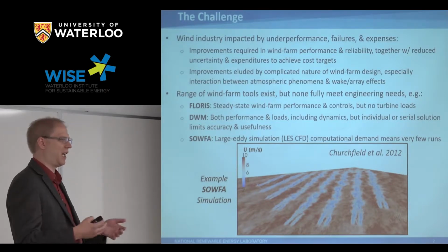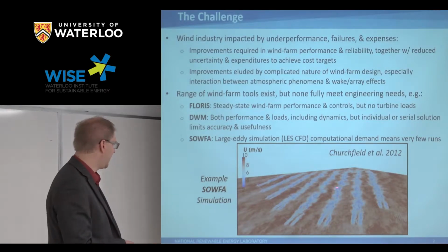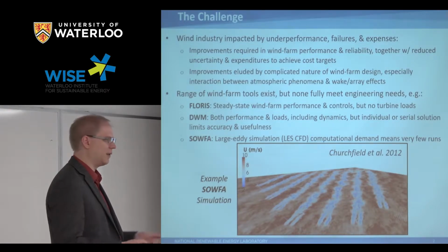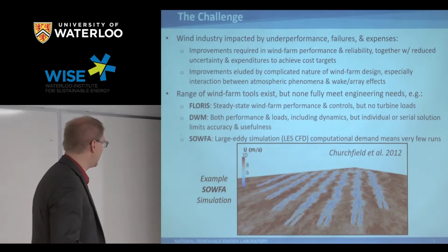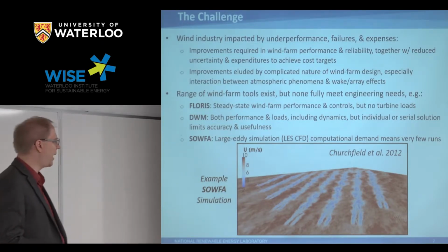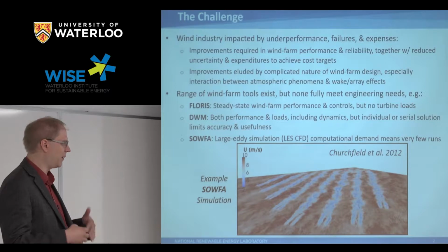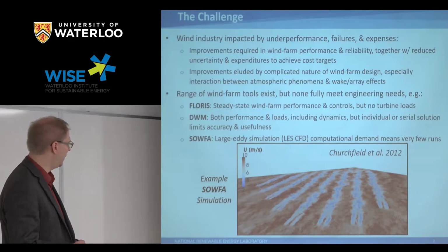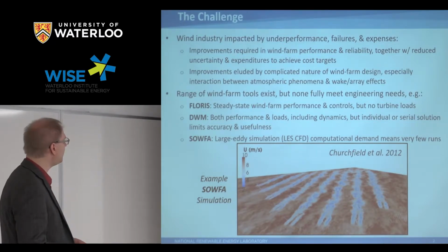And you can get a cumulative effect, but you can never in such a simulation say the downstream turbine can't tell the upstream turbine to do something, because it's done later in the calculation. So that's obviously a limitation. The other way these models have been implemented before is they only really look at one turbine. They pick another turbine upstream that represents the effect of the upstream flow, and they treat it like an actuator disk. And so that's kind of where we started a few years ago.